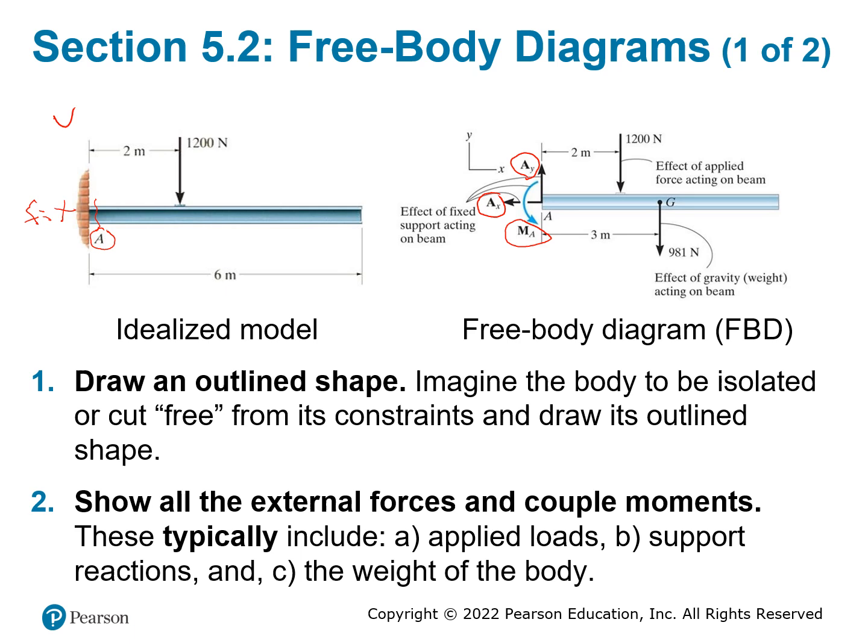Now, the direction of these reactions is arbitrary. Sometimes when you look at the problem, you will probably know what the reaction looks like. For example, in this example, if you push down a certain distance away from that with this much force, to prevent it from moving, this one must have a reaction force going up, right?